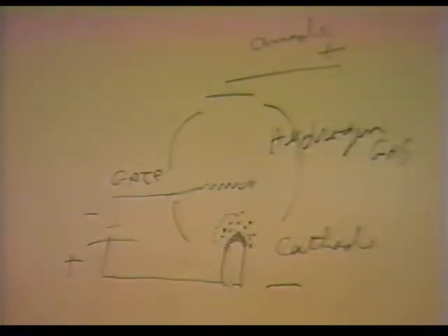In other words, if you wanted to hold off 100 volts, you would have a certain pressure. If you only needed to hold off 50 volts, anode to cathode, you would put more gas inside because that provided more carriers. Now, if you wanted to turn this device on, you notice the neon lights we have up here. They have a different gas in, but the principle is exactly the same, and that's why I wanted to explain this.